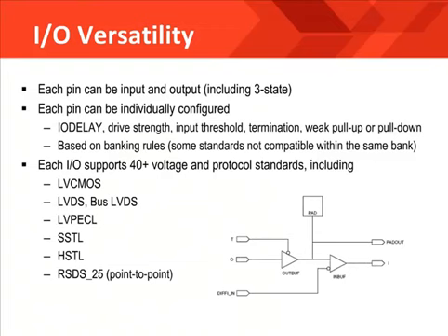The SelectIO resource was first introduced with the Virtex family of FPGAs several years ago. It has been enhanced with every new product family ever since. I/O standards have been added and selected to support what our customers require. Virtex-6 FPGAs support over 40 I/O standards, including those you see listed here. But check your datasheet to see if your I/O standard is supported. Note that there are memory-specific standards of varied classes, and differential standards that require 2 I/O pins to receive the signal. The differential signaling standards include LVDS and LVPECL. The single-ended I/O standards include LVCMOS, SSTL, and HSTL.